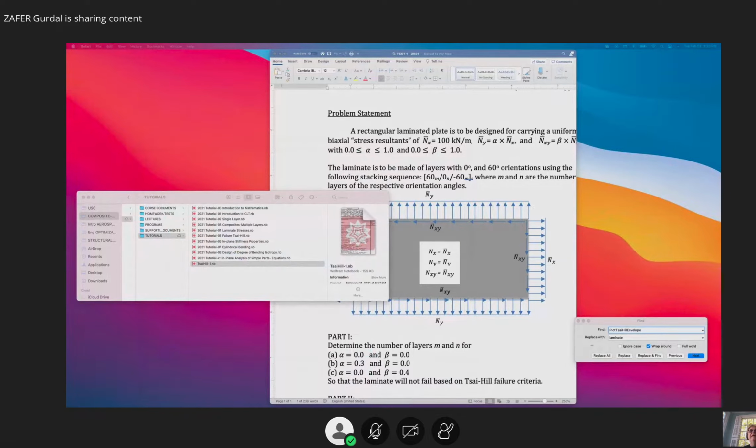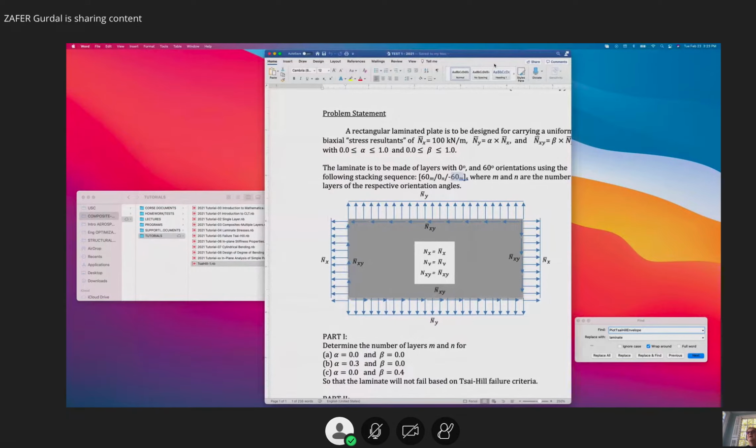All right. Now let's get back to, as I said, so far we are able to design a laminate. If we have done the analysis calculations and computed the laminate level deformations, from those you can compute laminate level strains. From laminate level strains, you can compute stresses in the individual layers. Then you can compare them to Tsai-Hill or Tsai-Wu or one of the other favorite criteria. You can design your laminates.